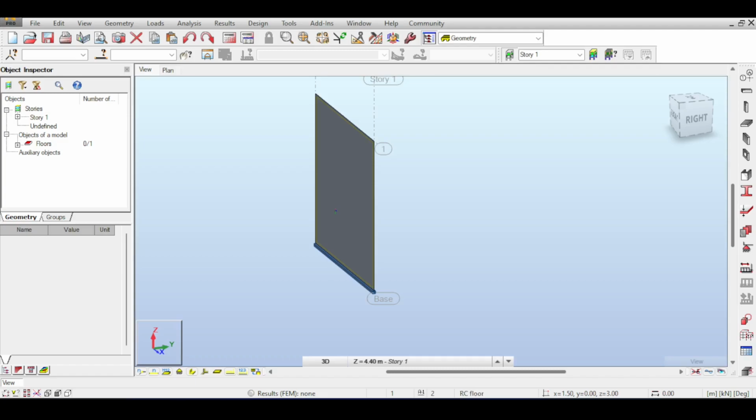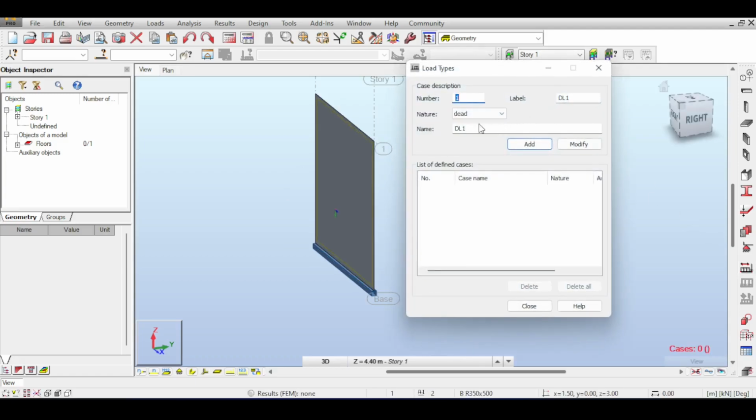So yes, sometimes retaining walls or basement walls, in that regard, are subjected to live loads and dead loads. For now, I'll just apply some geotechnical or soil pressure loads without any regard to dead load and live load, because I'm assuming that this only retains soil and that there are no live loads or dead loads around it. So I'll just open some cases, consider this to be dead, consider this to be live. And then here comes a little bit technical.